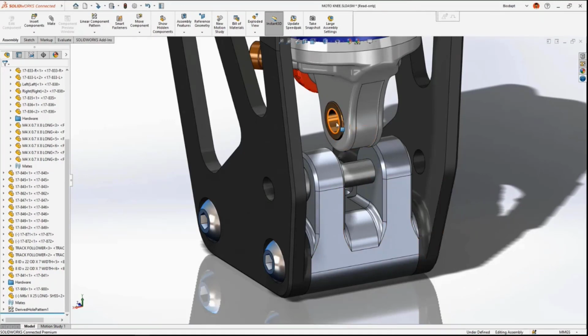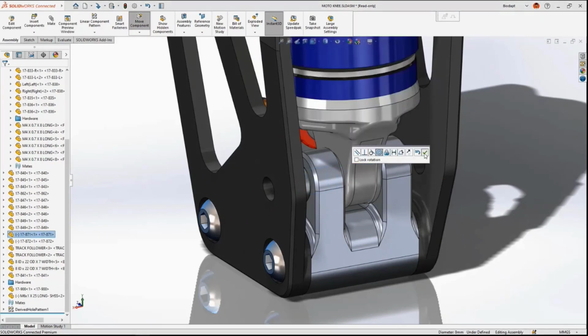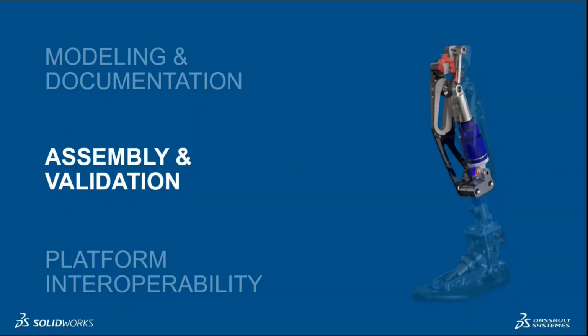We don't need to worry about this. Again, the same thing, surface to surface, drag and drop it. Automatically, the software will consider the mates. So like this, we have advanced mates, smart mates. We can use them. If you don't know anything about the mates you're using, you can simply use all these advanced techniques. Simply drag and drop near that particular face, and it will automatically create your mates, right? Well, this is ready now. Whatever changes I have done, this is fine.